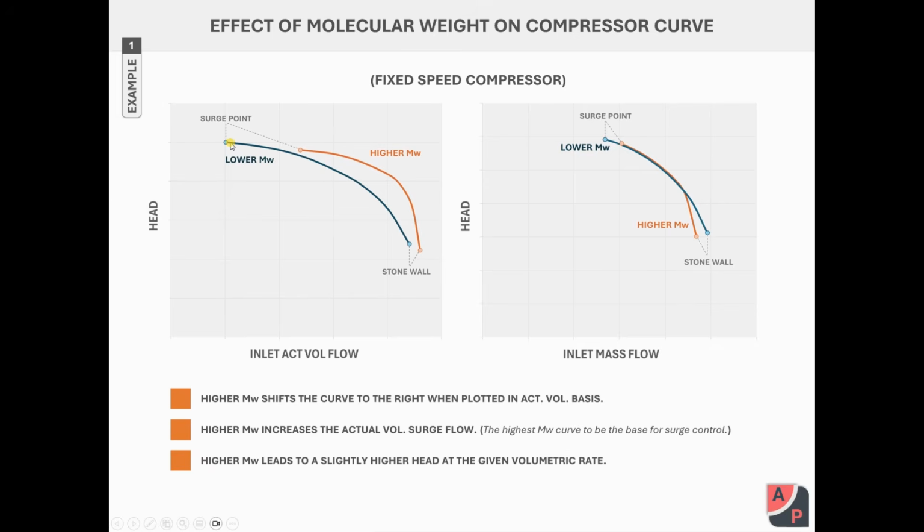In addition, there are two things when analyzing compressor performance. One analysis is based on having a curve and changing the parameters to see how the performance changes based on the given curve. The other one is how the curve itself changes based on specific conditions like molecular weight, which is related to the composition itself.